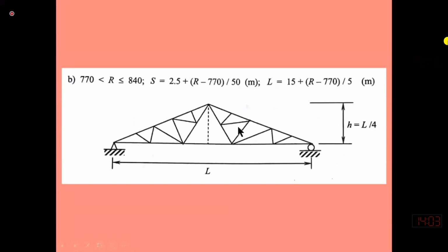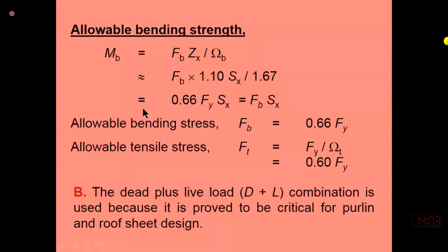So it means that once you have these points, you can join all the other members and compute the length of all members. This point is connected from here to here, and these members are connected. So you can determine the length of each truss member and give each one a number. You can apply the unit load, gravity or wind load, and perform the analysis.